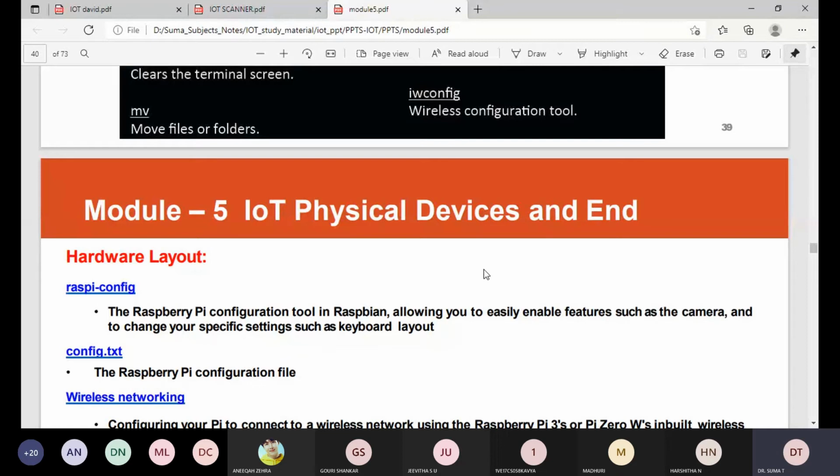For the first boot, plug in the keyboard, mouse and monitor cables. Now plug the USB cable into the Raspberry Pi. Now the Raspberry Pi will boot and a window will appear with a list of different operating systems that we can install. We recommend using Raspbian. Tick the box next to Raspbian and click on install. Raspbian will then run through an installation process. Note that this can take a while.